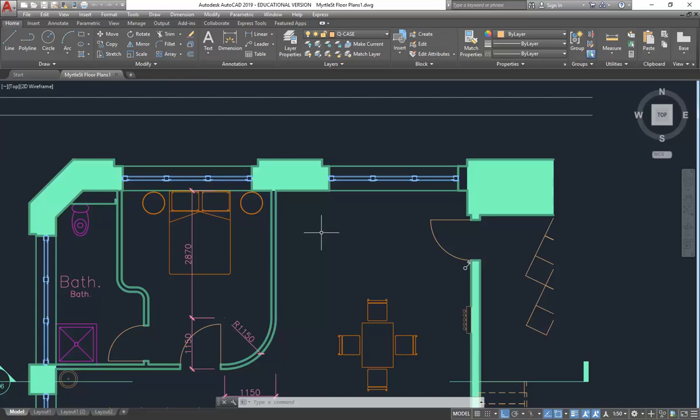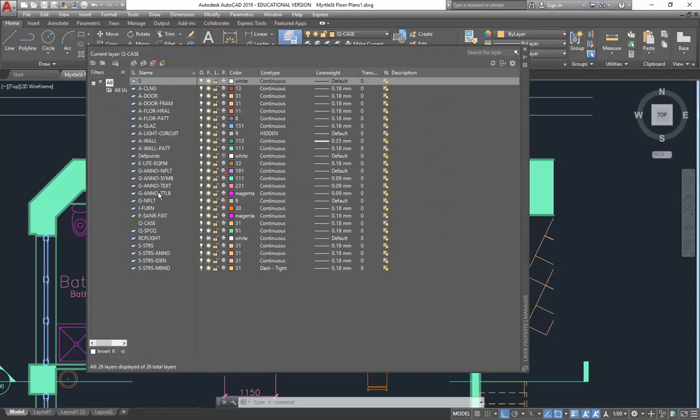Okay, so I'm just going to go through the setup of your kitchen joinery drawings, we'll call them. It's not just for joinery, but that's the focus. So I've got some layers. I'm just clicking on layer properties to show you that I've got some layers that have come from Revit that